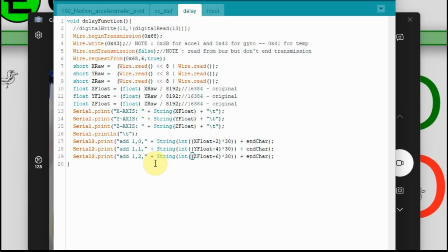Now this video is going to be tied to the one I did a few weeks ago with the Lux blocks and the spinning of the fan, because I want to hook this accelerometer up to measure the vibration on the fan. As I've also been told that you can tell the RPMs using the vibration sensor. So I want to see if that's true. I've never done it before, but I want to check it out and see. So I might also hook up a Hall effect device that will give me the actual RPM and compare it against what we see with the accelerometer.